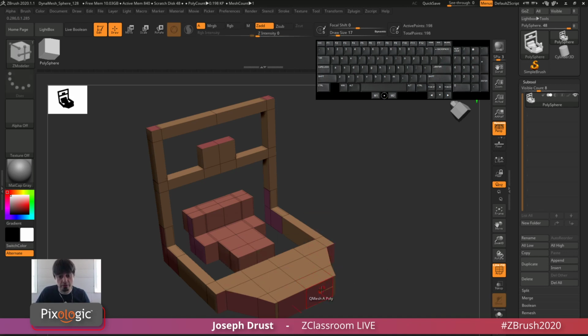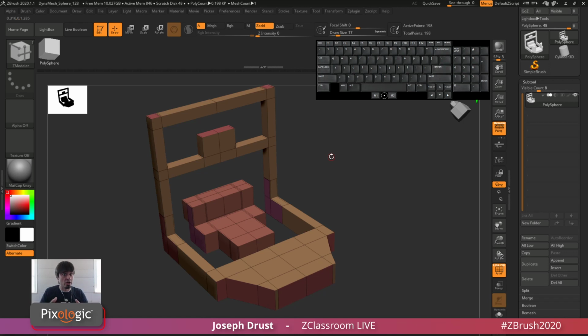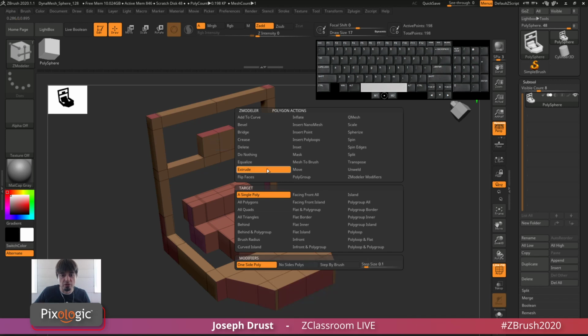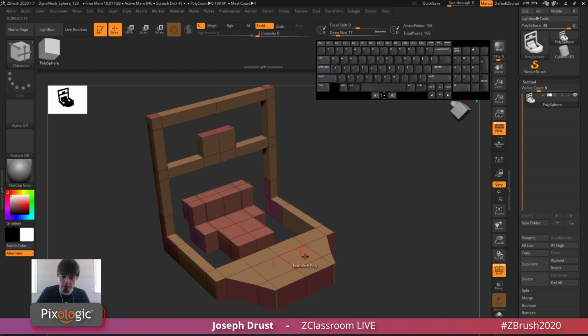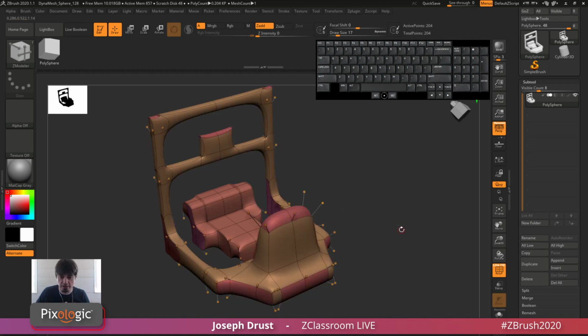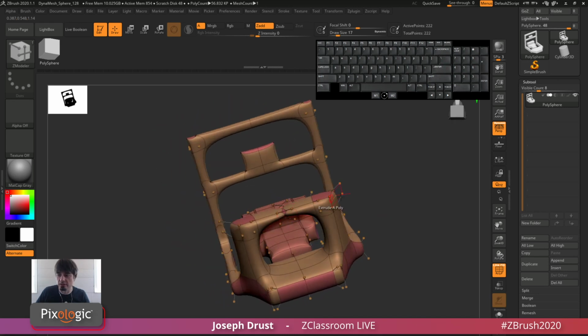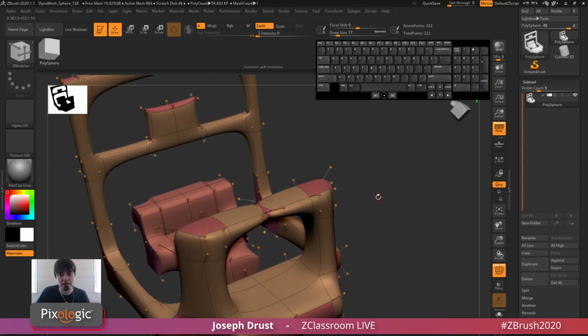Now there's also an extrude if you don't want the parts to weld, and this if you hover over a poly and press spacebar. In here we have the Q mesh, which is the one that's going to do the extrusion and the snapping or the fusing. And then we also have just the normal extrude, and this one isn't going to fuse. So if you came through and started dividing these up, and if I activate like this, and then say added these through here, you see it didn't fuse those parts. So it's not going to do the smart weld.